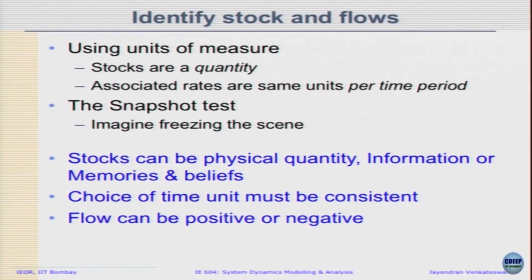Flows can be positive or negative. Please remember that we are just dealing with a simple simulation. It has no extra logic built into it. It is just variable names. So just by looking at the variable, you may have a sense of direction, like positive, or that this cannot go negative, and things like that. But for the computer, it's not going to do anything. You have to be careful in defining whether the sense of direction is positive or negative, and accordingly model the system.